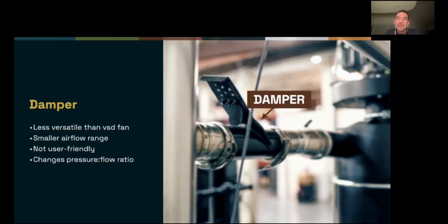So it's meant to decrease the amount of airflow, but again, it has a relatively small effect because the fan is still spinning at the same speed and working just as hard. And what happens when you close off the damper is you create a little more pressure in the drum relative to the airflow, but the airflow level changes very slightly. Are we caught up on questions?